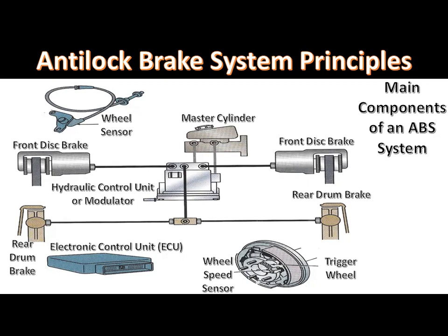Many ABS systems also have a red brake warning light. If this light is illuminated with the engine running, the parking brake is applied or one section of the master cylinder is low on brake fluid, caused by a pressure differential between the two sections of the master cylinder. In some ABS, the control module illuminates both the amber and the red brake warning lights when certain serious defects occur. Under these conditions, the ABS is disabled and the system will operate as a conventional power brake system.